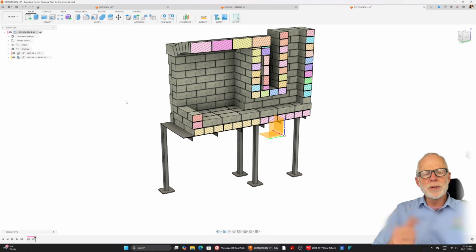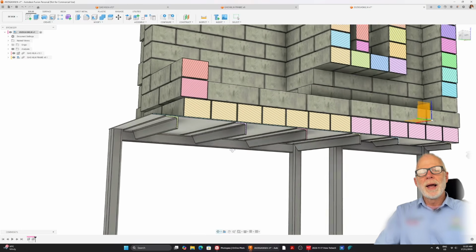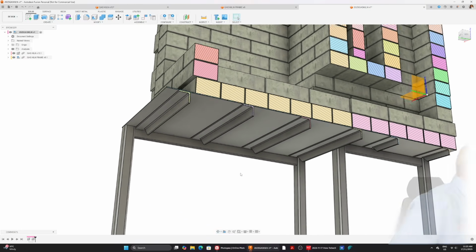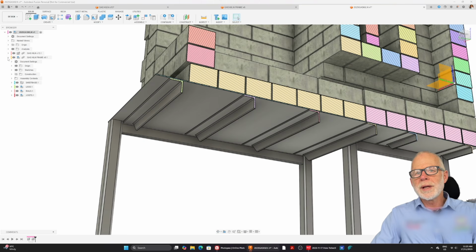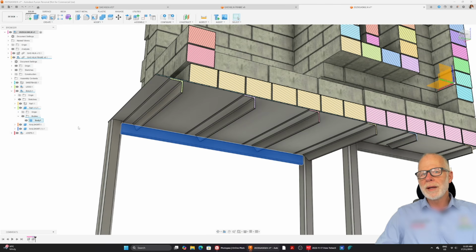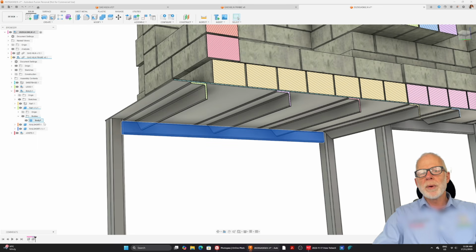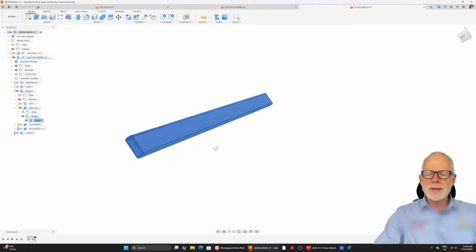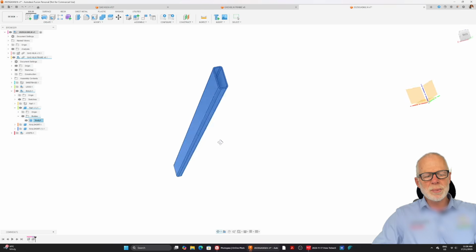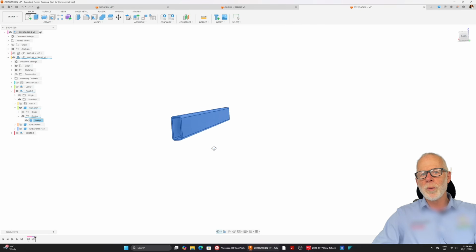Now this is a hobby project, and so it has to be cheap to build, and so here's my first question. Just how strong does this rail have to be? You can see that it's got several angle iron joists sitting on top of it, and above that quite a lot of fire bricks sitting on it, so there's a bit of weight there. So it's RHS tube, that is rectangular hollow section, 50 by 20 by 2.5 thick. Now I'm going to have to buy this RHS, and so what I need to know is what is the smallest cross-sectional area that I can get away with here.